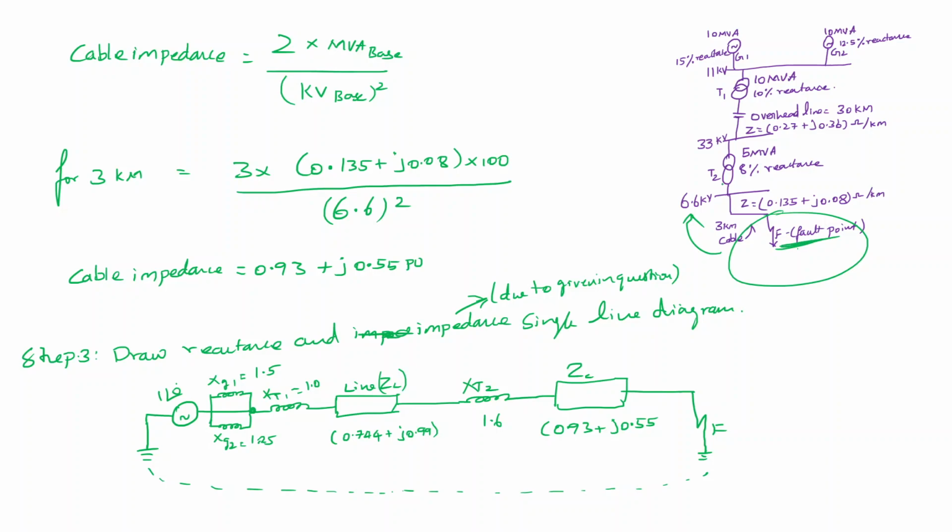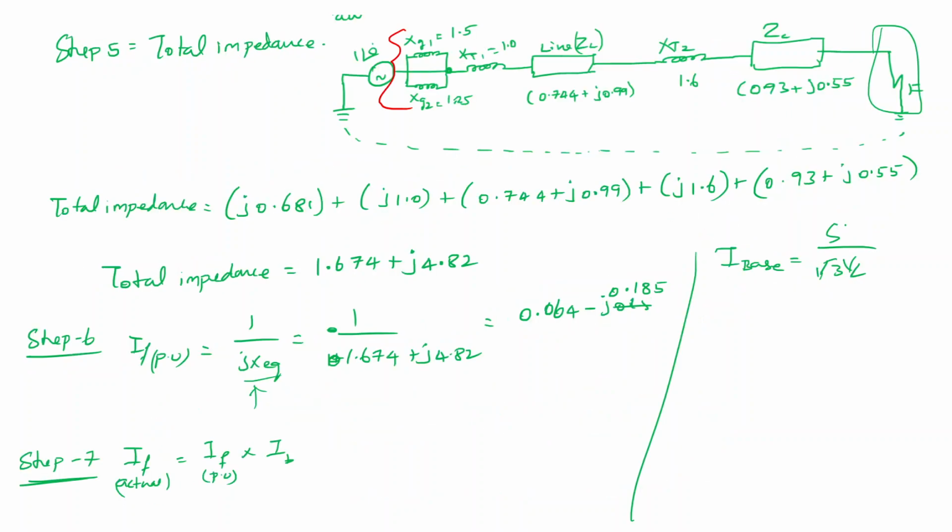At 33 kilometer, the third bus value is 6.6 kV. Obviously the voltage flowing here is 6.6, and also there is no voltage drop, but even though of small resistance, especially given in the question, there will be drop. But anyway, we can ignore this drop compared to the fault occurrence here. So we'll take the entire voltage as 6.6 kV here, right?